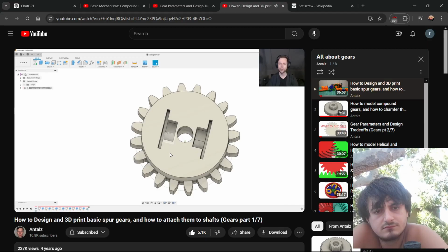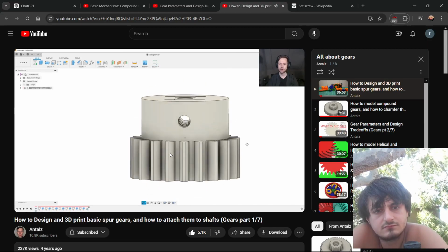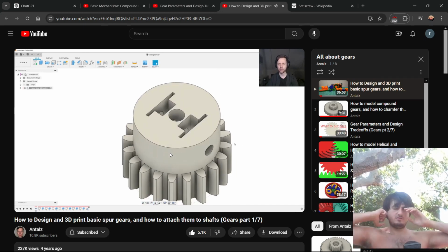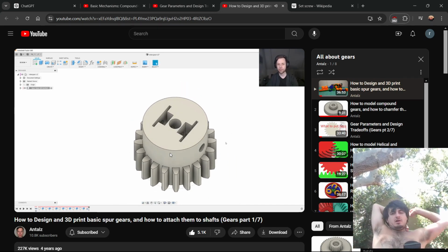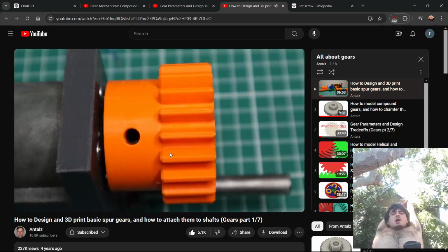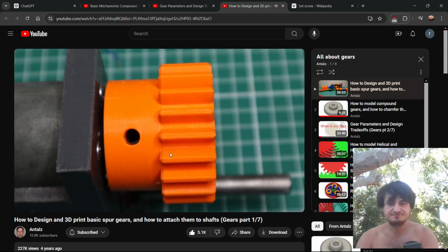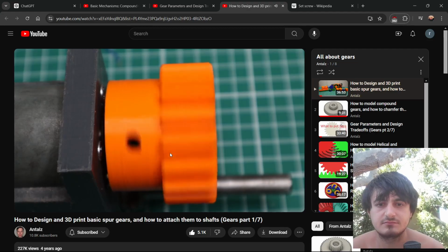I have 2 cavities for nuts, I have 2 cavities for the washers, and now if I look at it from this angle, I have 1 hole going straight through the gear. So now I can add 2 set screws to balance out the forces that this gear will experience, and thereby prevent the concentricity error. I've now mounted this new design to the motor. As you can see, if I give this a half turn, you can see the set screw on either side. And I will now turn on the power supply to show you the concentricity error.